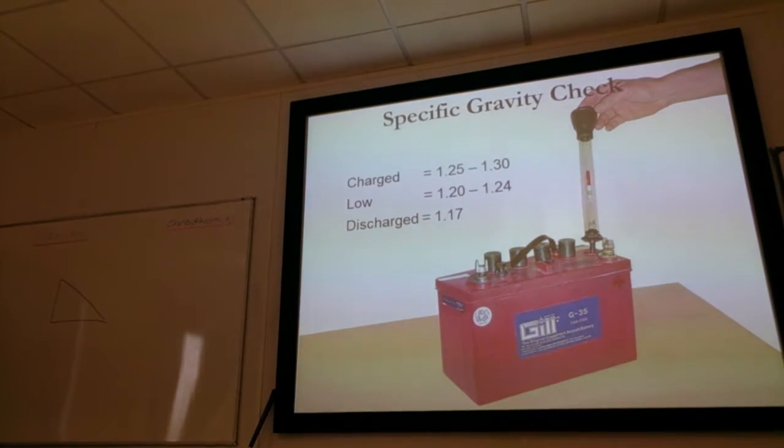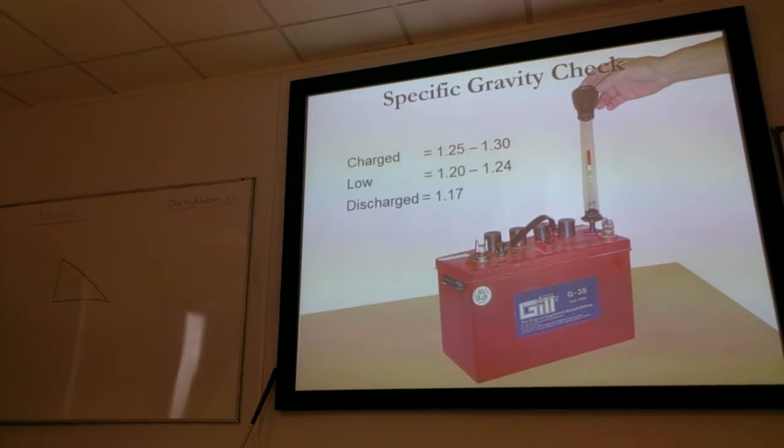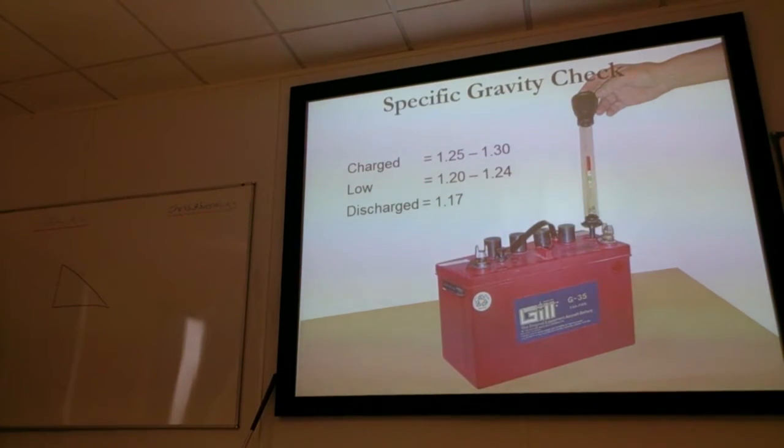What have you got in the aircraft to give you some idea of the health of the battery? Voltmeter. And how would you actually deduce the health of the battery from that? Just from the voltmeter? Yeah, absolutely. Put a known load on it, i.e. stick a light on or stick a pitot on. If the voltage immediately drops to 0, then you've got a dud battery. If it falls slightly but then stabilises, the battery's healthy.